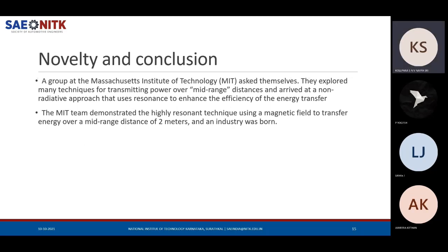Further improvements can be made to the project. The linking of the solar with the WPT is expected to be done in the future. This can be proceeded by modeling the PV arrays and studying the peak times of loads, when the vehicles come to the charging station, at what time the load is maximum. The MPPT, maximum power point tracking, can also be improved by using fuzzy logic.